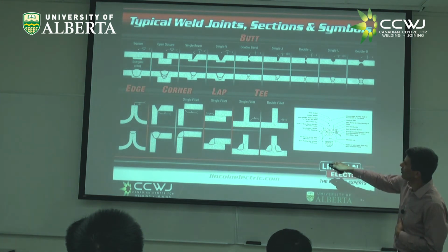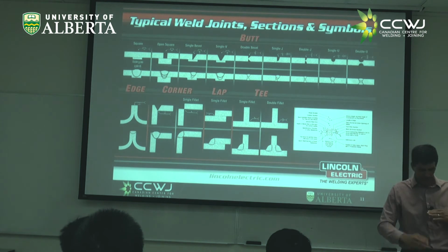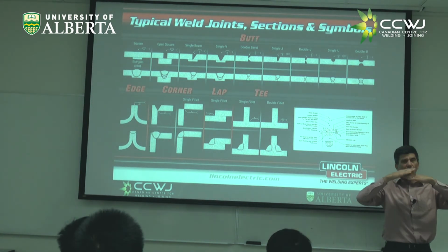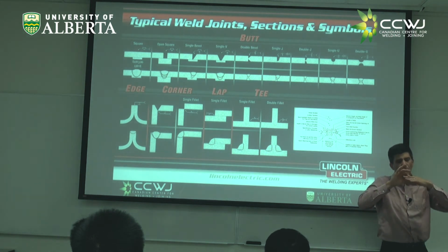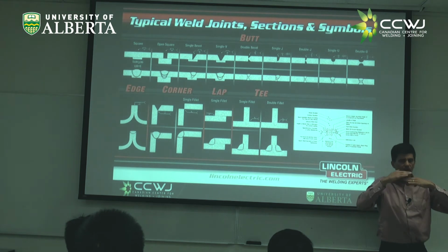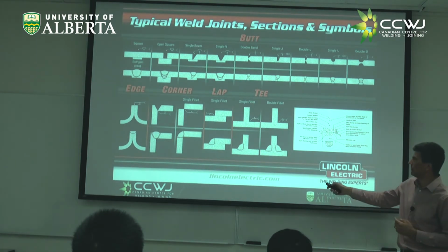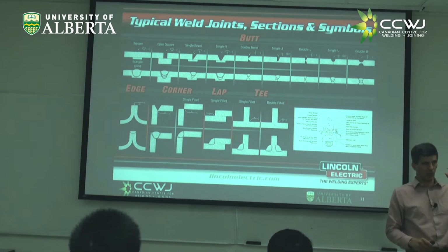Here you have what is called a lap joint. You see the plate is coming one way and the other is that way. It's like this. This is very used in the auto industry. But they use it with thin sheet and they would use spot welding. In civil constructions, they also use a lot of these lap joints too, but with thick plates.